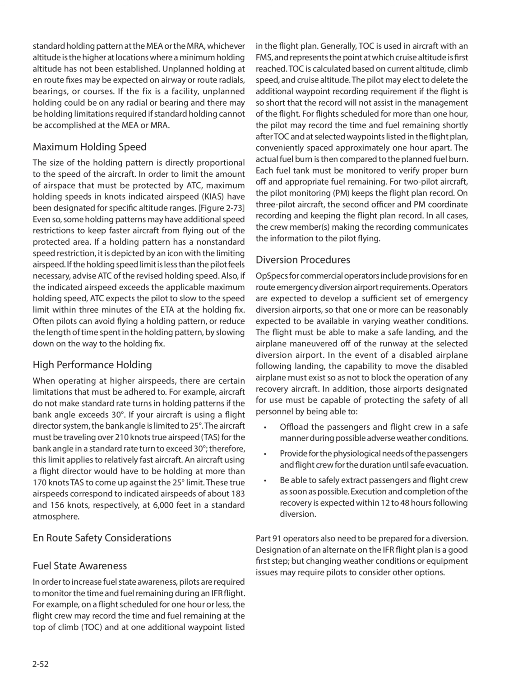Even so, some holding patterns may have additional speed restrictions to keep faster aircraft from flying out of the protected area. If a holding pattern has a non-standard speed restriction, it is depicted by an icon with the limiting airspeed. If the holding speed limit is less than the pilot feels necessary, advise ATC of the revised holding speed. Also, if the indicated airspeed exceeds the applicable maximum holding speed, ATC expects the pilot to slow to the speed limit within 3 minutes of the ETA at the holding fix. Often pilots can avoid flying a holding pattern, or reduce the length of time spent in the holding pattern, by slowing down on the way to the holding fix.